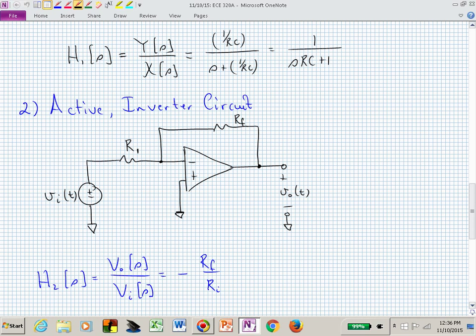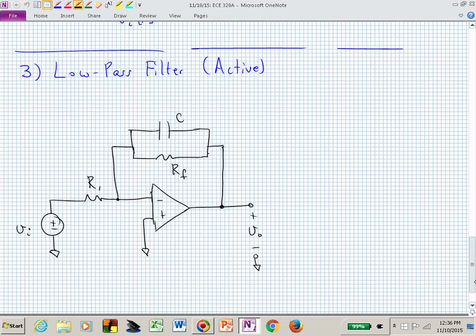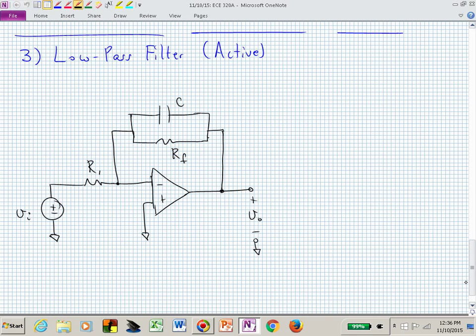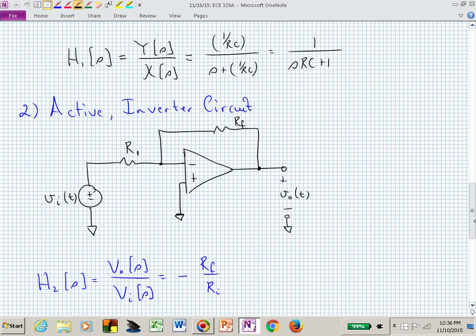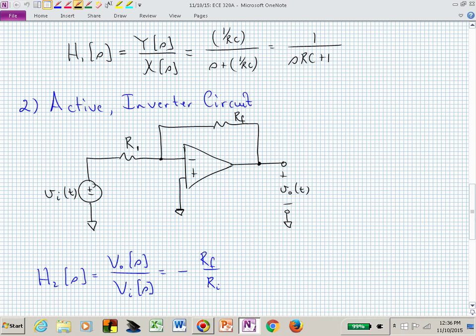The way that we have computed that transfer function might be helpful for many, many different circuits, and in particular, what if we bump it up a notch? This one, how does that transfer function change, or how does it vary with frequency? If I put in a sinusoid of 20 hertz and somebody else puts in a sinusoid of 1,000 hertz, how does the magnitude and phase, how is that influenced by this system?